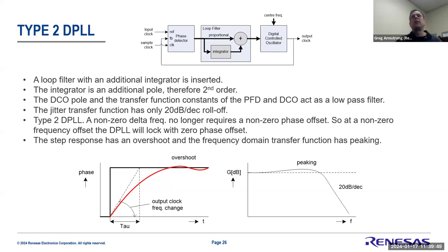So as I mentioned earlier, there are different ways of implementing a loop filter, but one of the most common ones is what we call a type 2 DPLL, which effectively means it uses a second order filter. And when you hear that, all it means is there's what we call a proportional term. And all the proportional term is, is basically the absolute difference of the error, right? So if the phase detector comes in and says your error is 10, then the proportional term is just 10. That's what's going to come in.